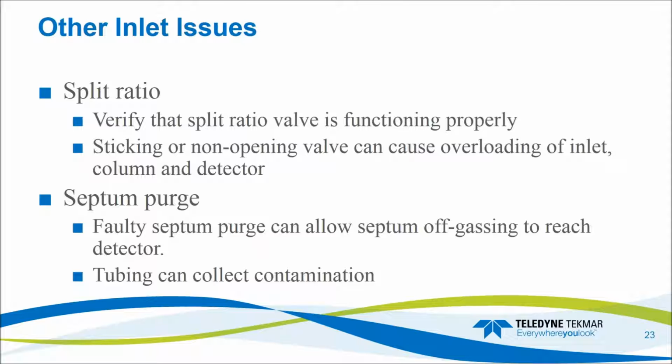If it's sticking or it's not opening correctly, it could be overloading the column, which is going to cause carryover. And then look at your septum purge. Is the septum purge working correctly? If not, you might have off-gassing from the septum making it onto the column, or you could have contaminants building up in that tubing for the septum purge and then backflowing back into the inlet and being carried in.